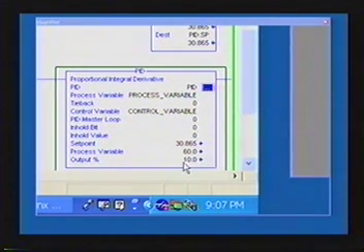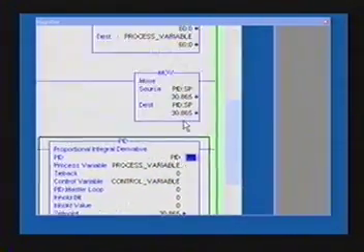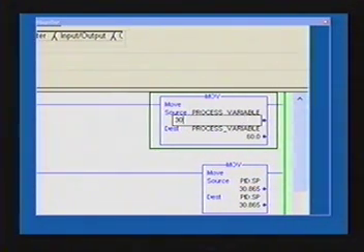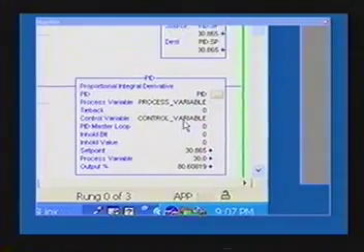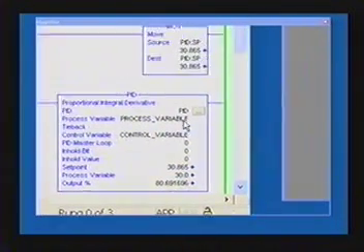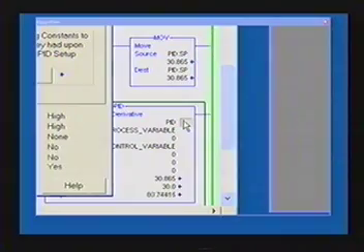So the PID routine said close the valve, right? But you're limiting the valve to 10% so that you don't deadhead the pump. So if we change this to something below 30.865, let's call it 30 even. And then it instantly jumped to 80%. I mean, it moved fast, right? So let's change how fast it moves.